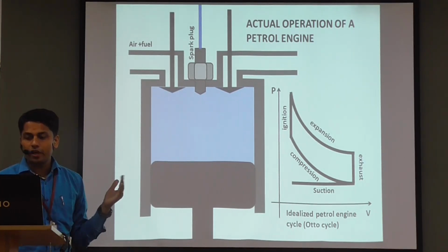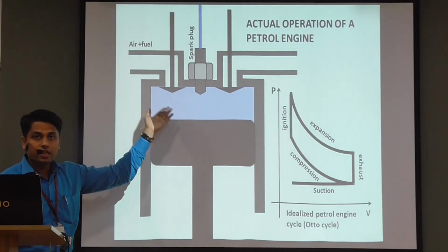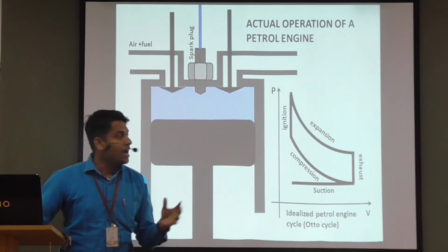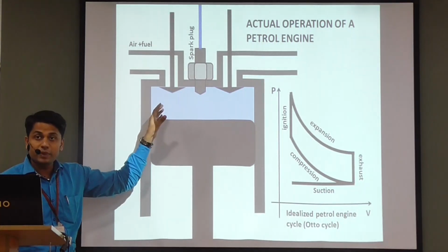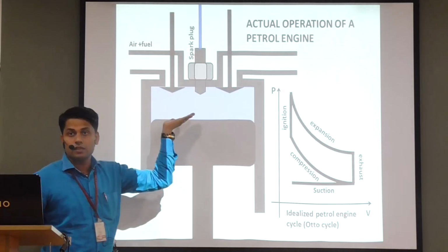The next stroke is the compression. During compression, as you can see, the inlet valve as well as the exhaust valve remain closed and the fresh air-fuel mixture which entered during the suction stroke is compressed.